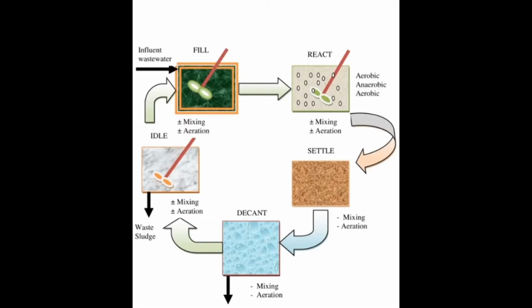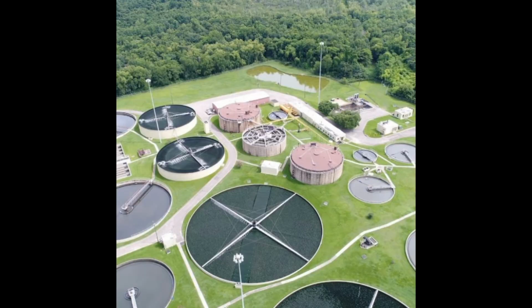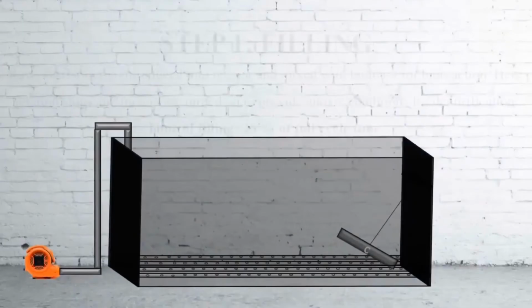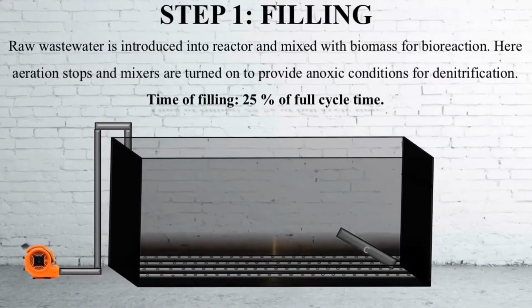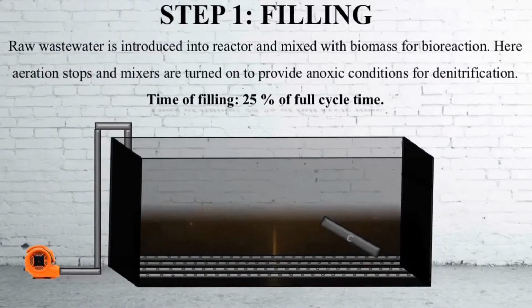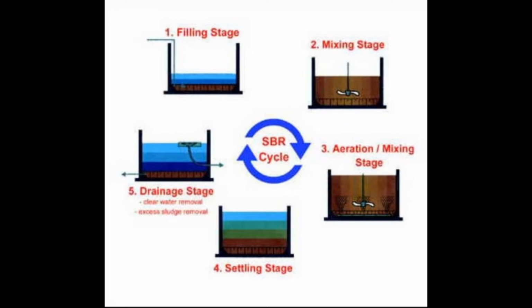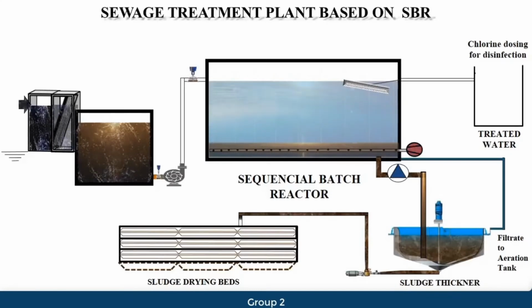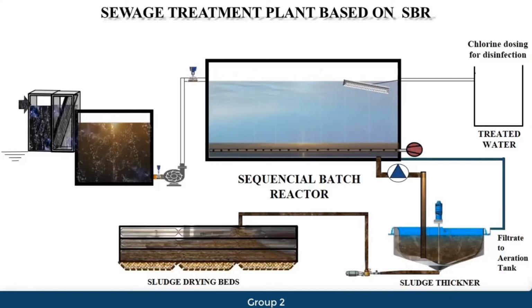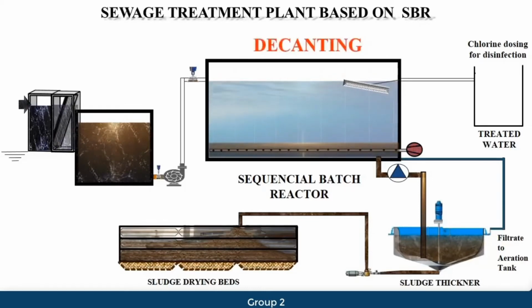The sequencing batch reactor (SBR) is a fill and draw activated sludge system for wastewater treatment. In this system, wastewater is added to a single batch reactor, treated to remove undesirable components, and then discharged. Sequencing batch reactors, or sequential batch reactors, are industrial processing tanks for the treatment of wastewater. It treats wastewater such as sewage or output from anaerobic digesters or mechanical biological treatment facilities in batches.